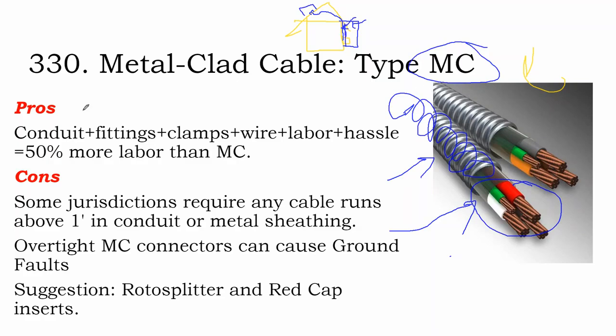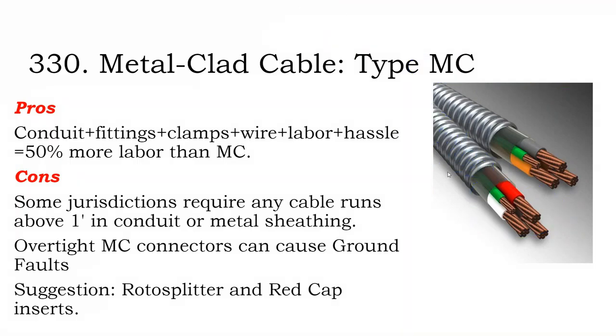That simplifies the installation, because instead of taking your conduit and snaking it over the side of the roof and around the roof and then around the roof again and then down to the inverter, you can just drill a hole in the roof, throw your MC cable over the other side, and land on your inverter. It's much faster, and I feel much better knowing that the cables of the solar array are protected by the home structure rather than exposed to the great outdoors.